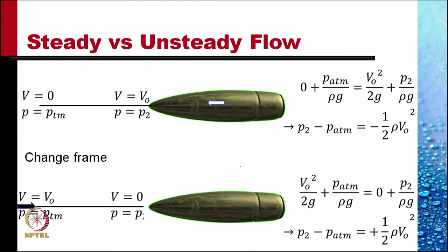Moral of the story, the Bernoulli equation in the form that we derived is applicable only to steady flow. So unless we can ensure that the flow is steady, we cannot apply the Bernoulli equation.